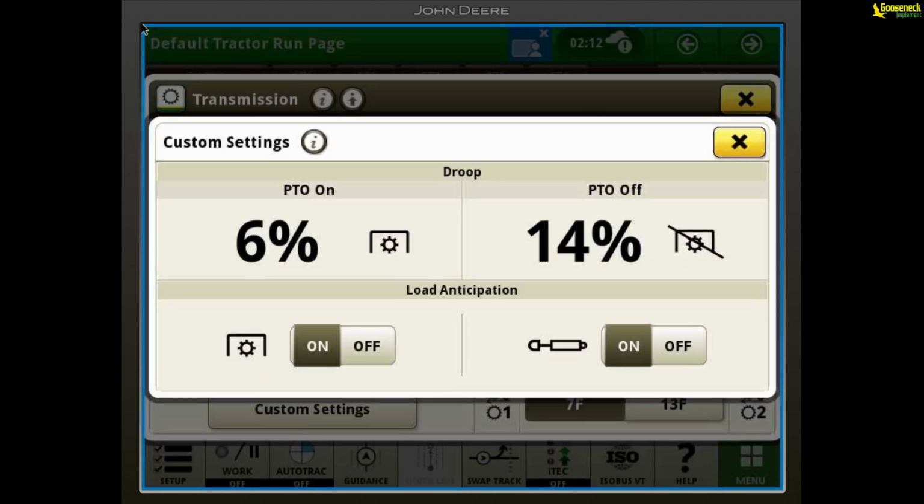Make sure to turn off the load anticipations for PTO and SCV. This way the operator can use these functions and not disrupt the Eco mode. For example, if SCV load anticipation was left on and the tractor was pulling an air seeder, every time the fan is engaged, it would not perform the Eco mode because of an active SCV.